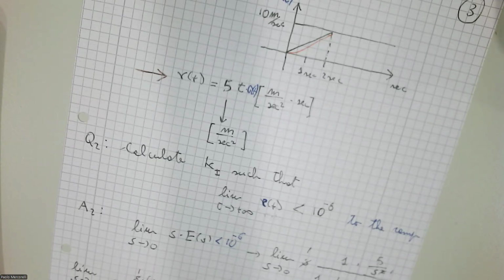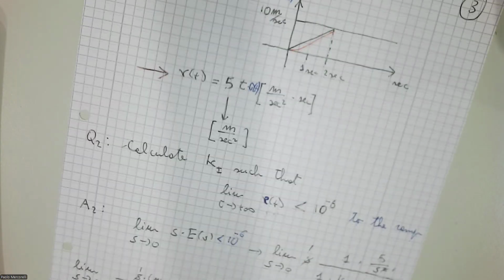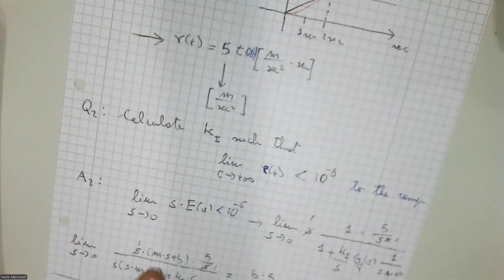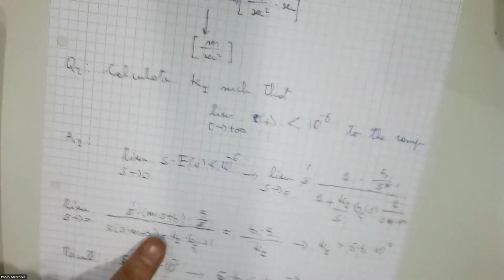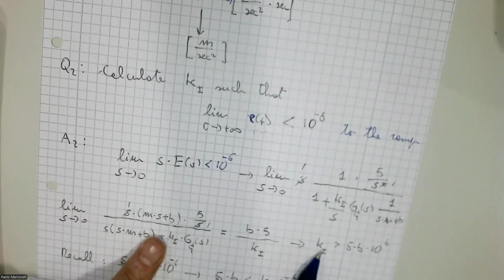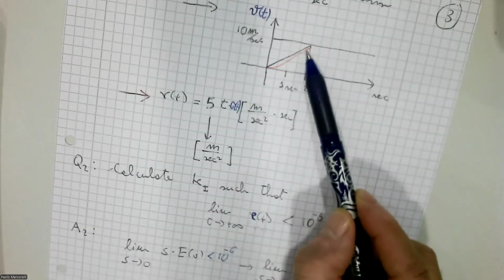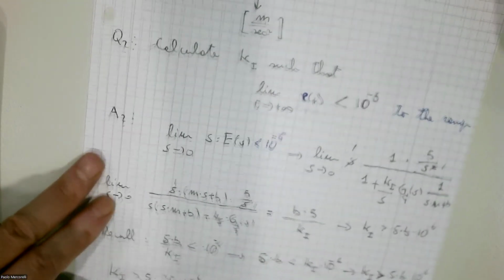But believe me, our system will follow my ramp with a bias, because the type 1, I think with a pole in the origin, will never achieve the ramp, but will be in a ramp with respect to the reference with a bias. This means if you have a very large Ki, it could be that we really obtain a good approximation. But the risk now is that we have an overshoot. You remember the red color curves. Now I show you the picture of what I intend.